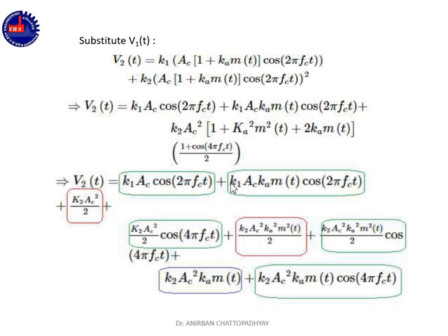So suppose we fixed our cutoff frequency here at FM, or the message frequency of the message signal m(t). That means the low pass filter will pass all the frequency components below the message signal frequency of m(t), and any frequency component above that will be mitigated.